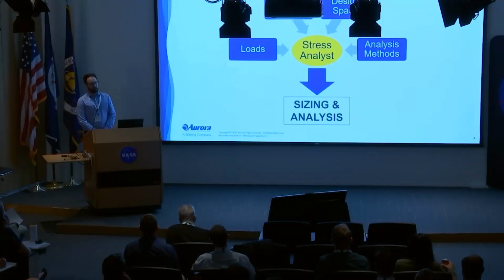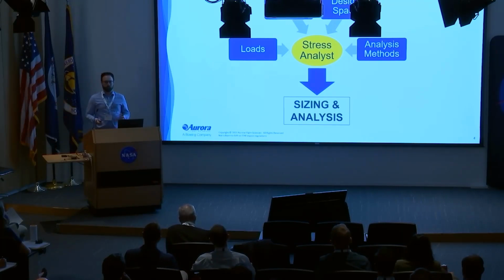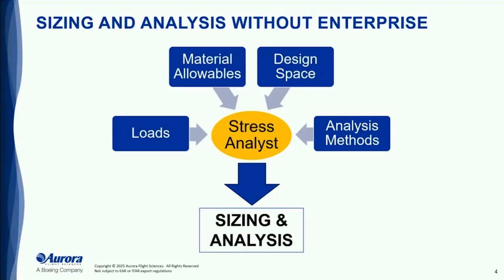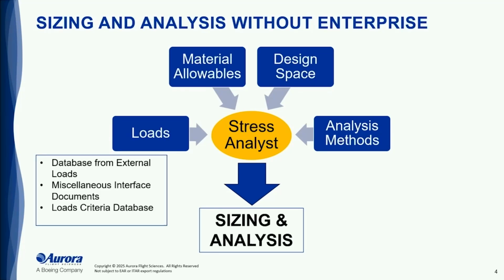So when a stress analyst is going through, there's been a lot of great topics on how stress analysts become kind of data managers as we go through and have to pull information from a lot of different sources. So from a loads perspective, we have loads from external load sets or reports, internal loads models, miscellaneous interface documents for payloads, cargoes, pylons, and any criteria that you have set for what your requirements are driving for your program.